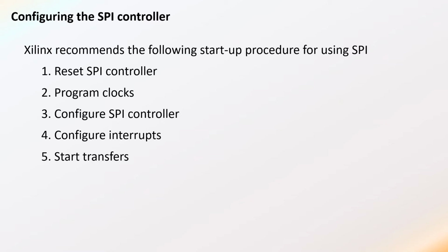When you write that known key value to an unlock register, only then are you allowed to change how the port is configured or to reset it. And the thought is that would be extremely unlikely to happen randomly. To randomly write the single address where the unlock key is stored, and then to write the exact right data, it's just very unlikely. So it's just a little more protection to make sure that applications don't accidentally overwrite or reset those sort of IP blocks. So I'll talk about that on the next slide.